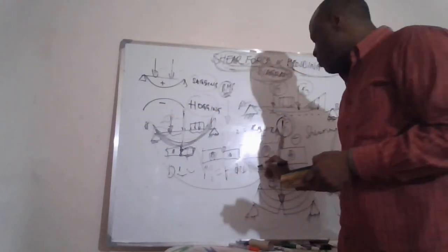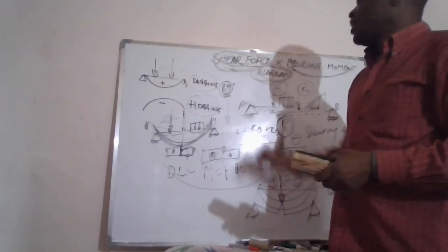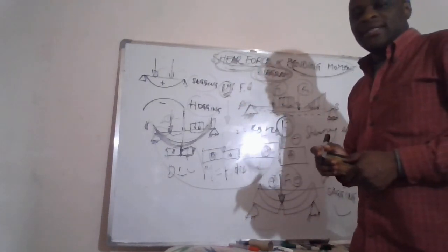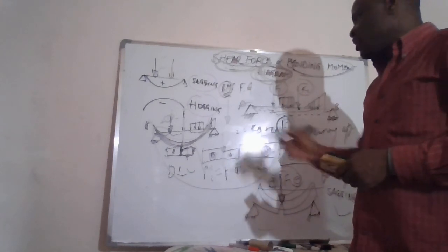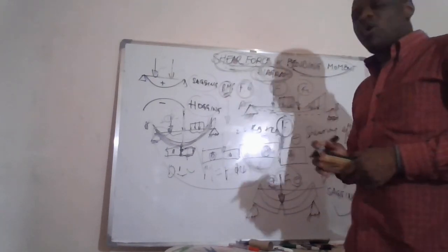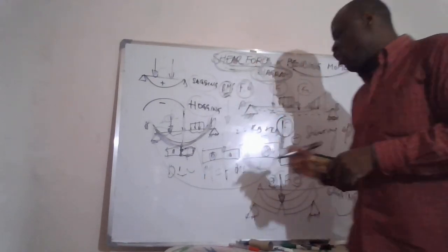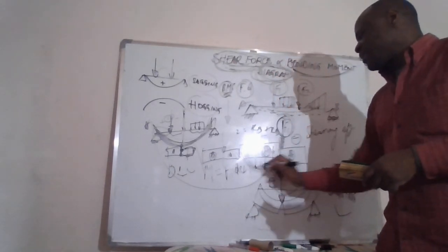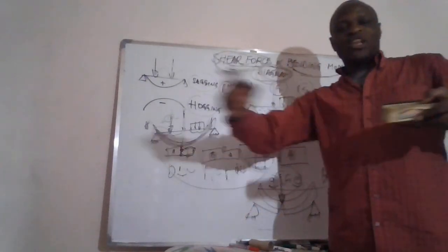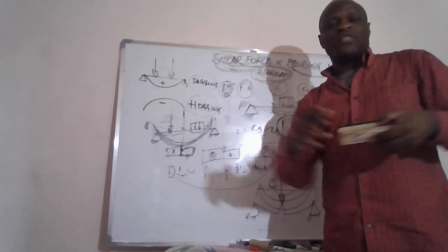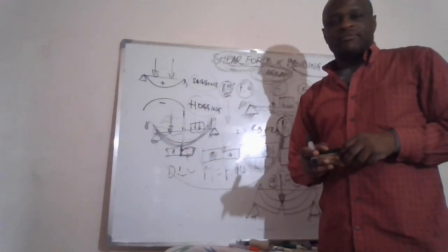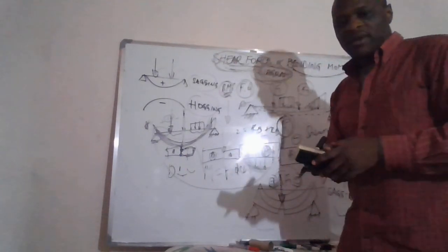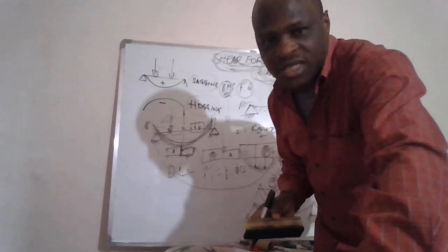But the bending moment is just a moment, and a moment is force times a distance to the pivot. Here we'll apply the sum of algebraic moments on each point that will be considered as a temporary pivot along the length of the beam. This is what it's all about, the shear force and the bending moment. Then we'll take some examples in the next session.